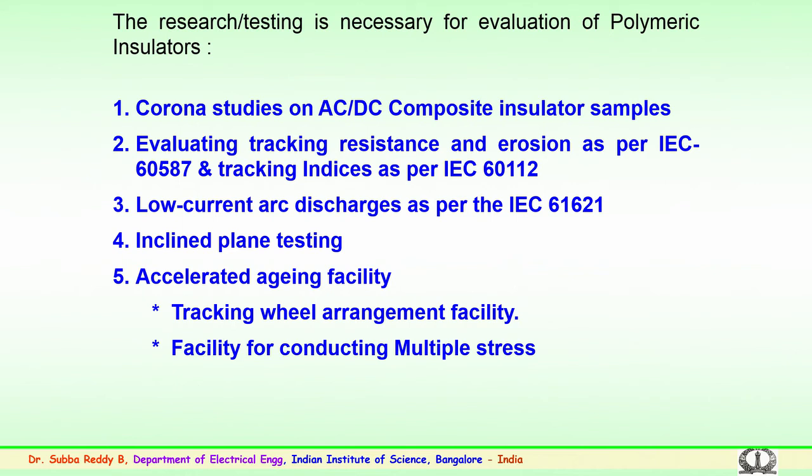In the field this insulator is likely to experience multiple stresses like the effect of temperature, the effect of humidity, the effect of ultraviolet radiation from the sun, and also the ultraviolet radiation which may come from the corona control rings, the corona induced UV rays, and due to fog, rain, and pollution. Several of these aspects have to be simulated to see whether the insulator withstands over a period of time.